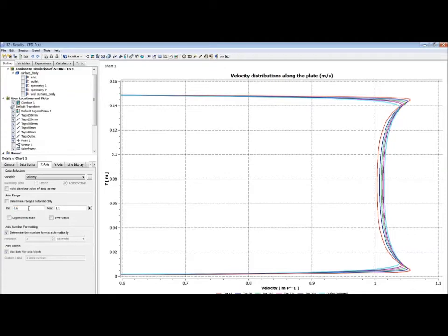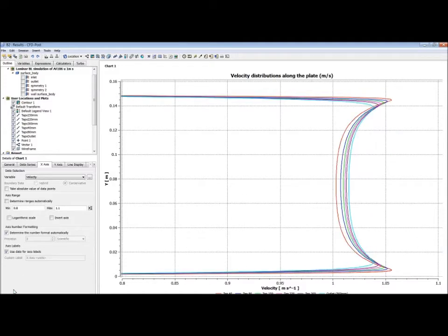We can probably make that slightly larger again. Right, so the first thing to clearly see here is that we do not have a classical laminar flow parabolic profile in the center. So there's obviously a development of the flow going on, which is probably quite unwelcome, but it's a consequence of the boundary condition that we've used, 1 meter per second.